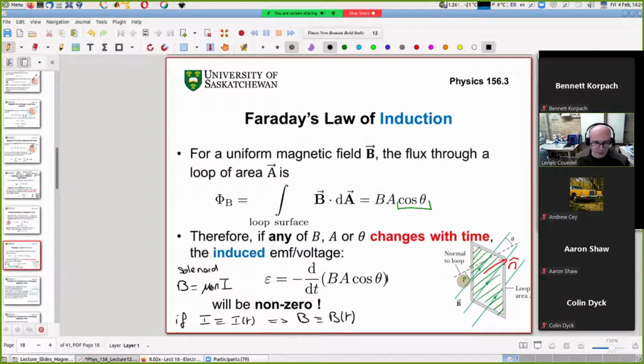So like the alternator of your car or the dynamo of your bike, or a power plant, like a coal power plant or a nuclear power plant or a hydro power plant. What you do is you have magnets turning in the middle of a coil, which is the same as a coil turning around magnets. So you have a changing magnetic flux through coils, and that's how you convert mechanical power to electric power. Okay, so Faraday's law of induction explains why we are able to generate electricity.